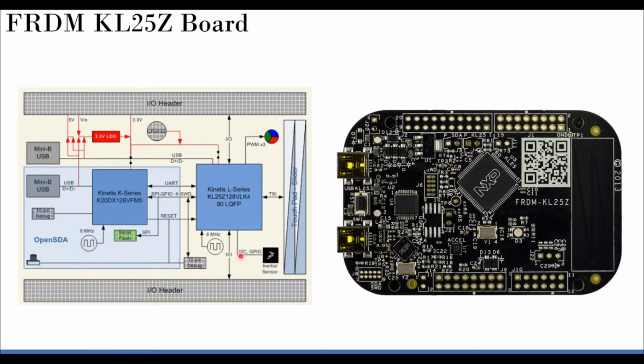But on a very high level, I will tell you what all are there. You do have the Cortex M0 Plus processor, which is sitting right here, and the name is Kinetis L series. Inside of it will be the Cortex M0 Plus processor. And you do have 128 KB of memory, which we discussed in the previous session. If you go back and see the code part, you will see that it's 128 KB. Totally this can support around 4 GB, which is supported by Cortex M0 Plus.